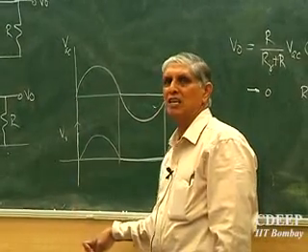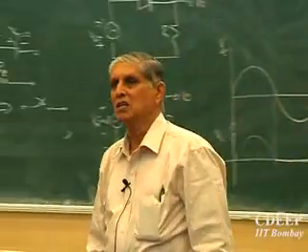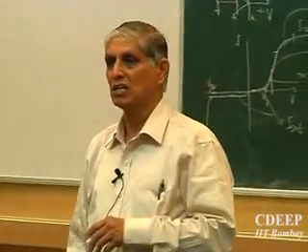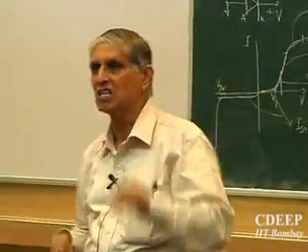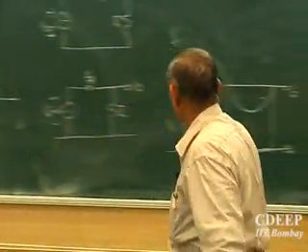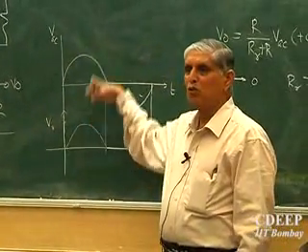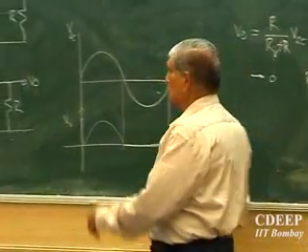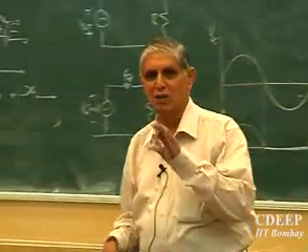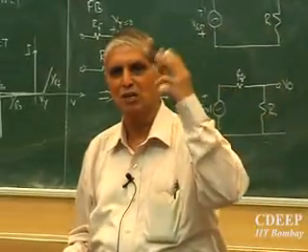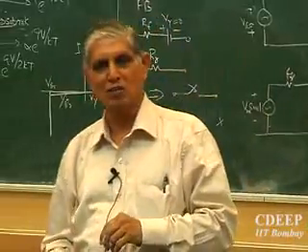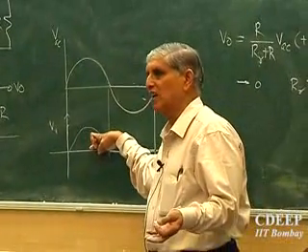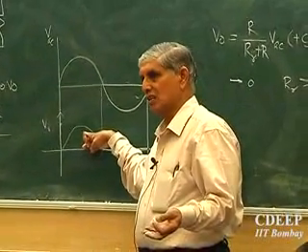What is the difference between AC and DC? AC means it's alternating between plus and minus. DC means unidirectional. It does not mean constant. It's a unidirectional current. So this voltage is now unidirectional. So you have now converted an AC signal into a DC signal, and if I put some capacitance, I can even make a DC value fixed. If it charges to the maximum value, it will become a constant DC value as well, if I need. Or I can take an average of this and find what is the average DC from this cycle. Is that point clear?